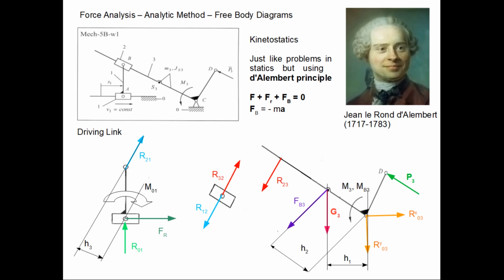And the kinetostatic analysis can also be solved using the analytic method you learned during your static course, because you remember that when you have, let's say, a structure at the static equilibrium, then to analyze the reaction between all of the elements of the structure, you have to assume that all of the forces, the external forces as well as the reaction forces, summed over should give you 0. And you know from the statics the so-called free body diagram method. When you have a complex structure, you, let's say, disassemble the structure into its elements, and for each of the elements you have the static equilibrium equations.